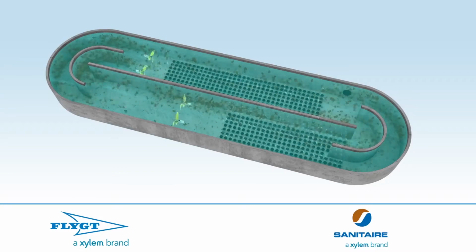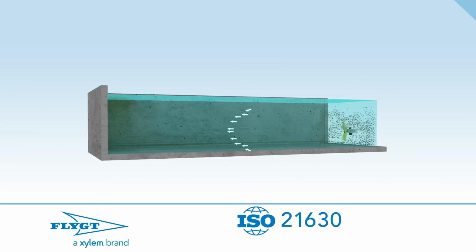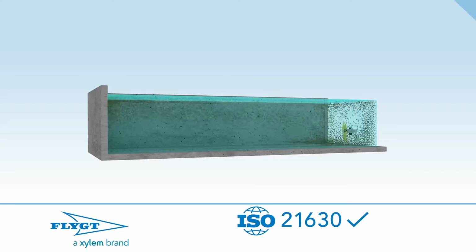Regardless of the tank type or shape, bulk flow is created by one or more mixers imparting thrust into the fluid. This thrust, which is in the form of a jet of water, moves the fluid and does the most intense mixing. Remember, when comparing mixers, consider only those tested to the ISO 21630 standard. This is the global standard for measuring thrust and will ensure that you are making a legitimate and valid comparison.